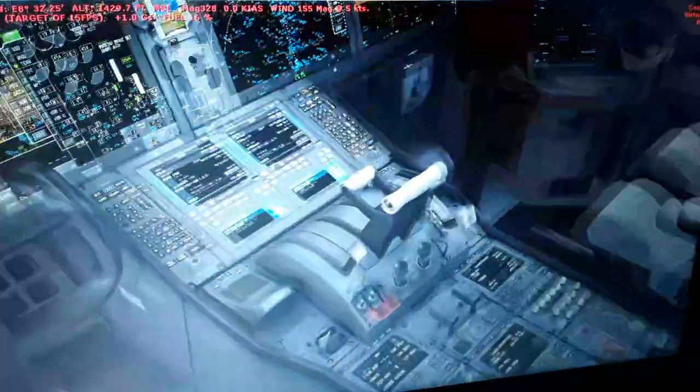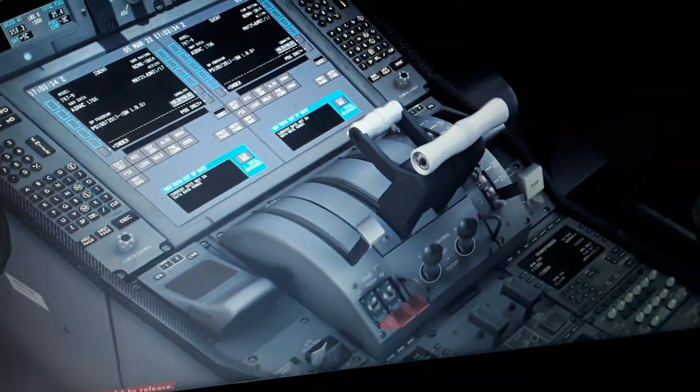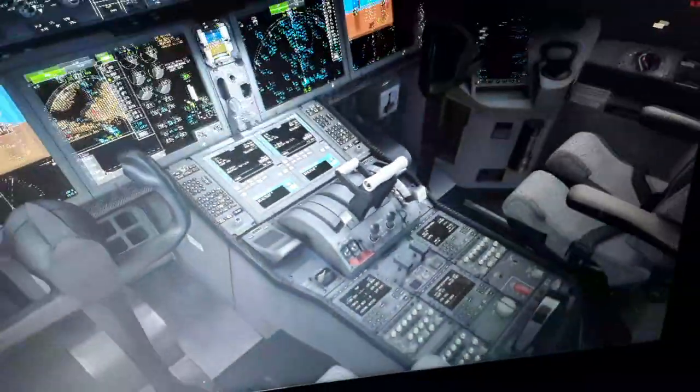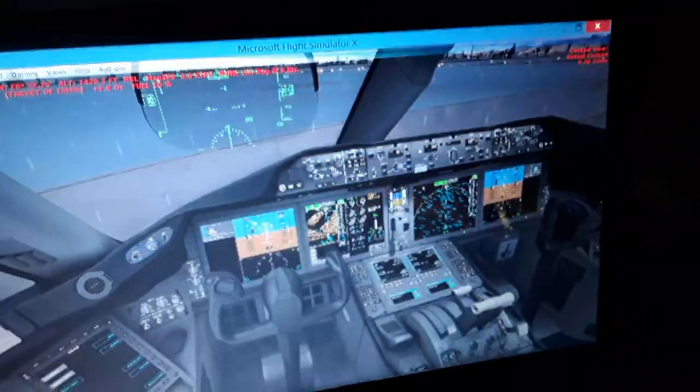So we have also the speed brakes, which are secondary flight controls, the thrust levers also. So I will show you how to use all the flight controls of the Boeing 787. In the flight simulator I use this side stick, so it controls the yoke of the Boeing 787 for climb and descent, also the ailerons and the spoilers for making banks left and right, and the flaperons using the control wheel.